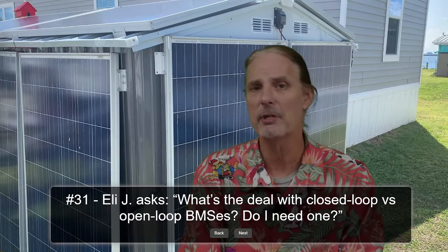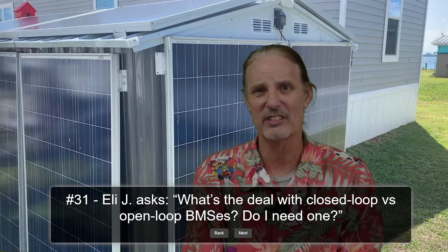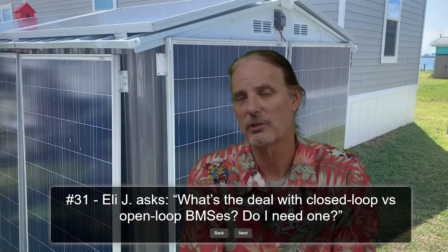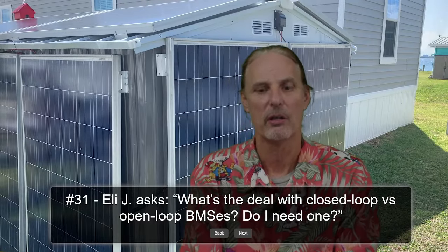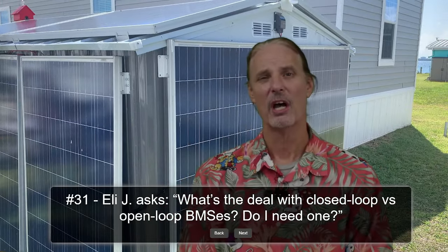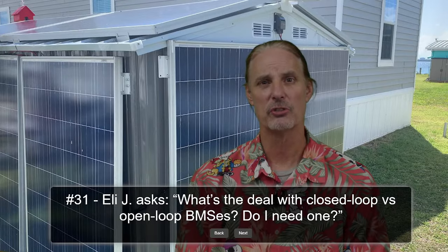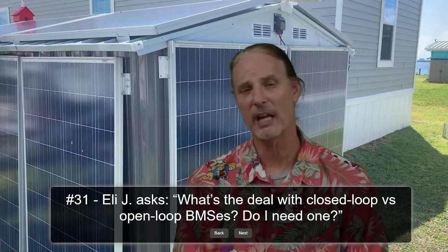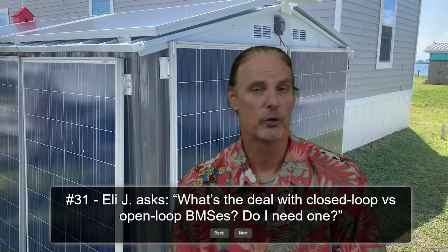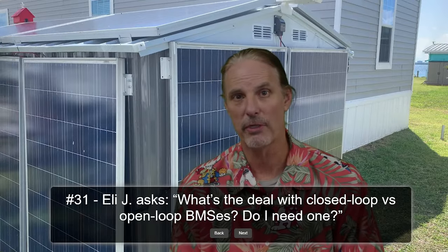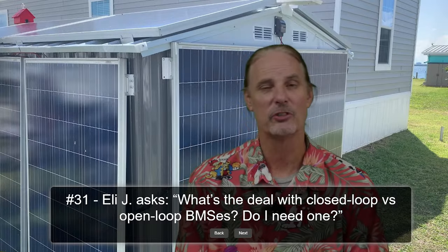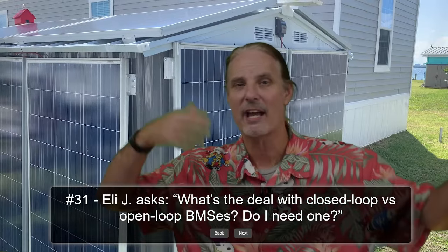The open loop is what we've been using for ages and ages. Most of that technology isn't anything new. Do you need one? Well, the determining factor is how automatic the system that you have is, and how much you're relying on that state of charge to do things. I use open loop and I use the Victron SmartShunt for my state of charge. I could feed that into my inverter and control it with that, or I could hook it to my EG4 batteries and use that. The problem is when I added the DIY battery, that put the whole problem into the mix.